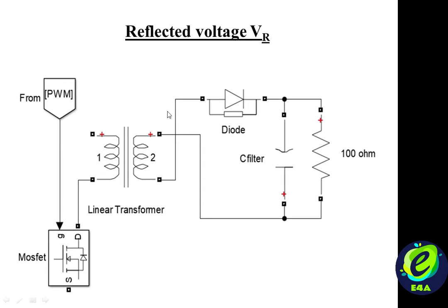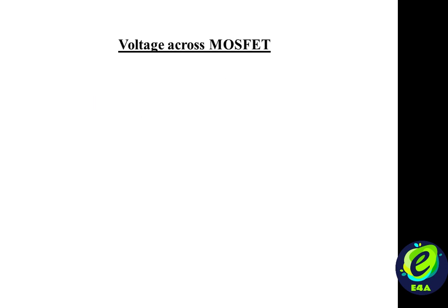Now let us assume that the output voltage of our flyback converter is 12 volt DC. The drop on the rectifier diode is 0.7 volt. Then one can say that the voltage of the secondary winding is 12.7 volts. When this secondary winding is conducting, the voltage gets reflected to the primary side of the transformer, amplified by a factor of the turns ratio. This voltage is denoted by VR. The MOSFET also has to withstand this extra voltage stress.